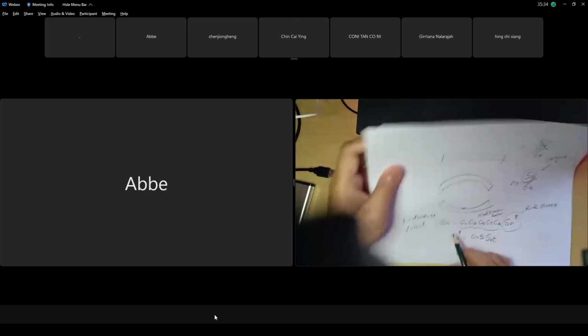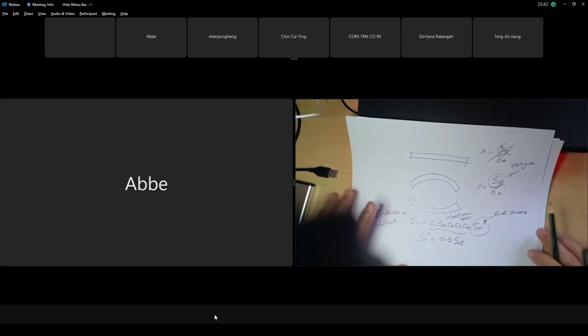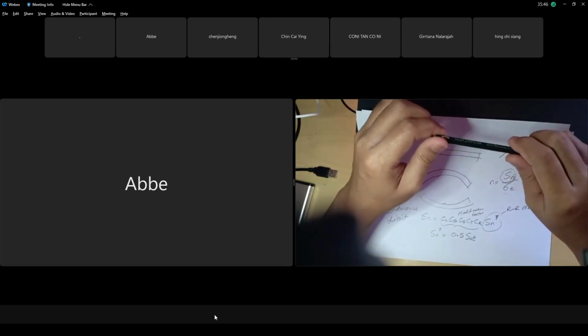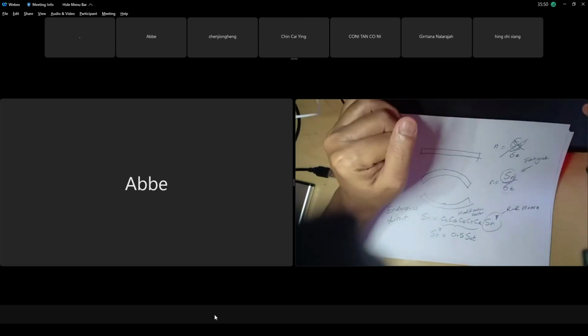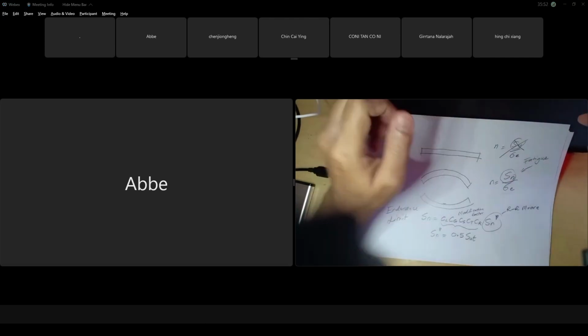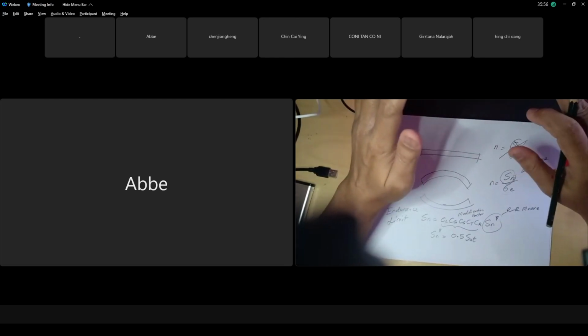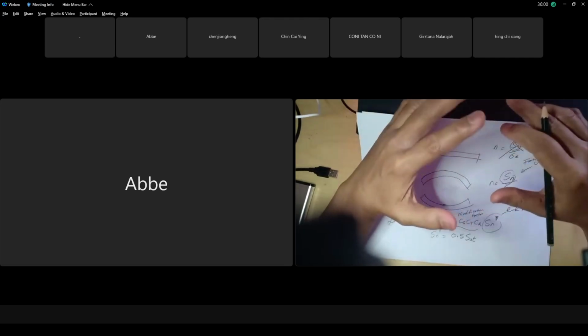Once you have calculated your endurance limit, you get your safety factor, where the safety factor is SN over your sigma equivalent. But this is a rough equation, I will explain later, because there are other things we need, like the fatigue stress concentration factor, for shoulders and grooves, which have stress concentration. Later I will explain. Also about sigma mean. Okay, that's a basic explanation about fatigue analysis, a rough introduction.